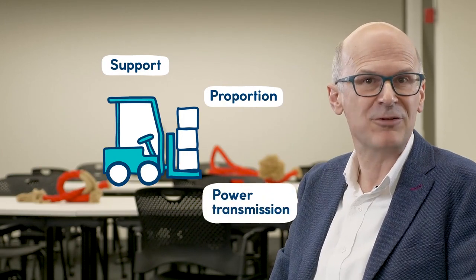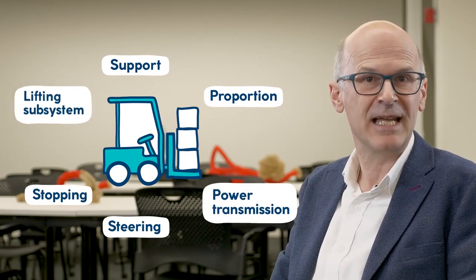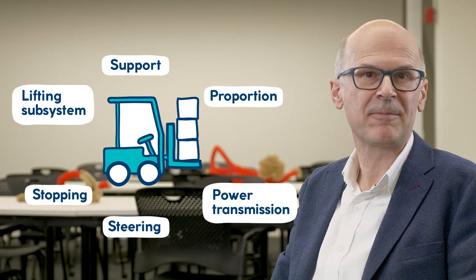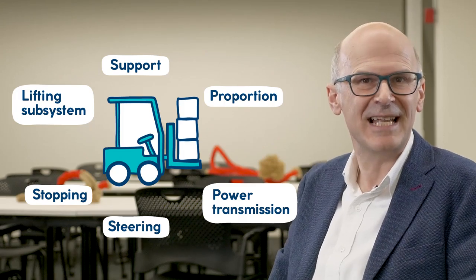The use of morphological charts requires consideration of the function of subsystems rather than their specific details. A pallet-moving device might consist of support, propulsion, power transmission, steering, stopping, and lifting subsystems. In using a chart, a selection can be made of one means of fulfilling a subsystem from a given row. An overall solution is then synthesized by pulling all of these elements together.